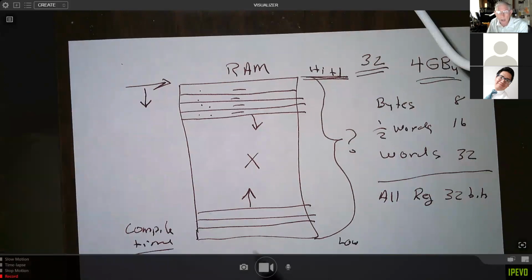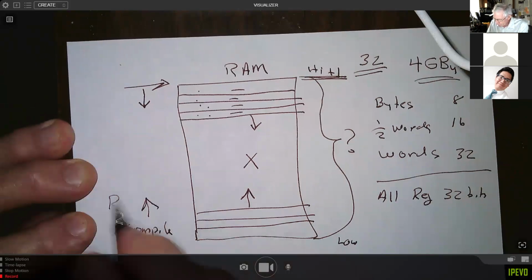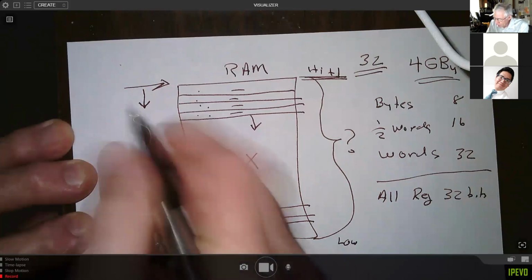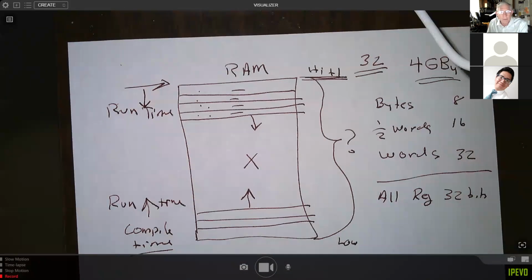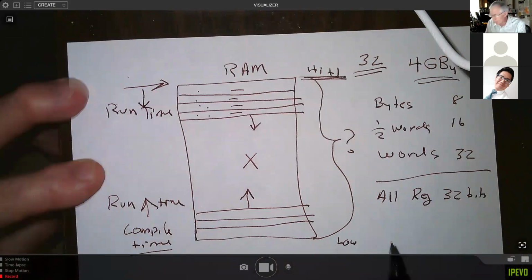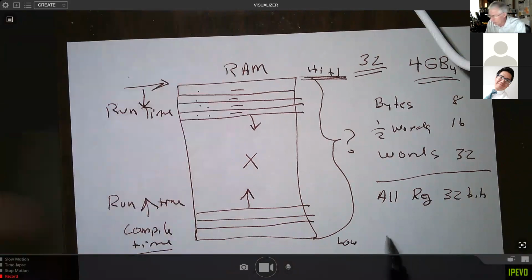for a lot of the memory locations, but not all. You're also going to add some of the memory locations during runtime. But all this is runtime. So this is a dynamic event, and unless the operating system, first off, you have to be using an operating system to make this work. And if you're using bare metal code where you don't have an operating system monitoring this, then you're not going to know when these two clash. So if you run out of RAM, you may not know it, but you're certainly going to have some problems. Your variables will be corrupted, and your return addresses may very well get messed up, and you won't ever get back to where you need to get back to.